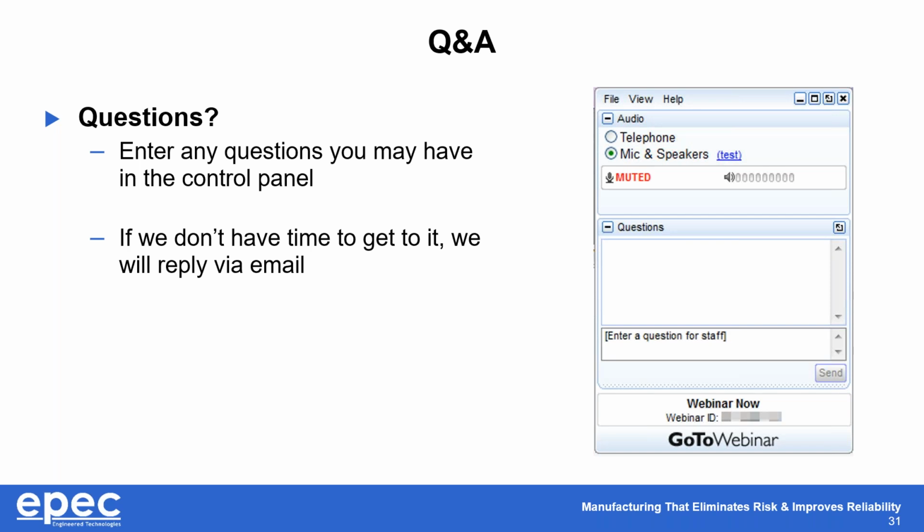Second question we received regards reliability of the various constructions. And the question is, is a flex with stiffener construction as reliable as a rigid flex construction? The simple answer to that is, in the majority of cases, yes, it is. If it meets the balance of the design requirements, it won't bring a reliability concern along with it.